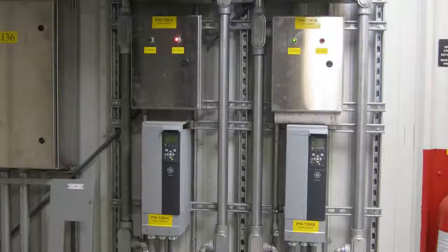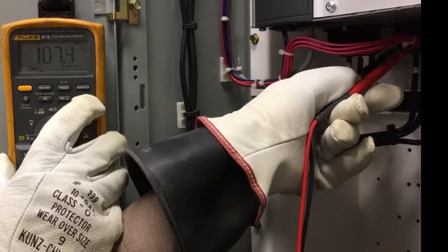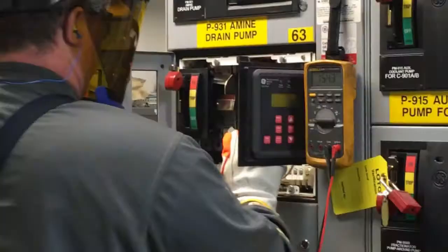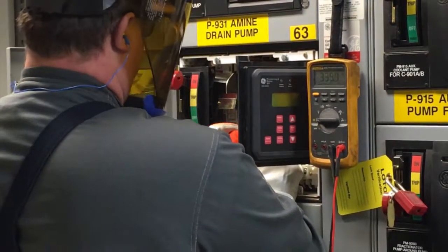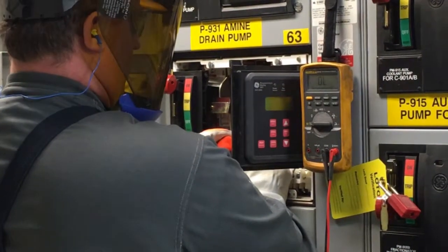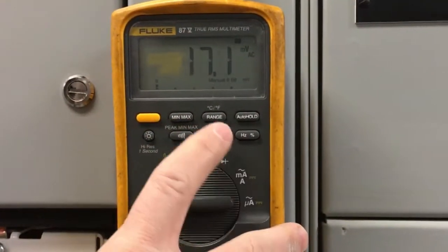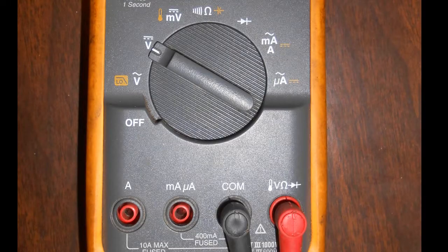A common measurement that requires this filtering is a variable frequency drive or inverter output. There are two important things to remember when using this feature. The first thing is never use a low-pass measurement to determine the absence of voltage for safety purposes. A higher voltage than indicated may be present, but at a higher frequency. The second thing to remember is the meter will switch to manual range mode and will require that you select the proper voltage range.